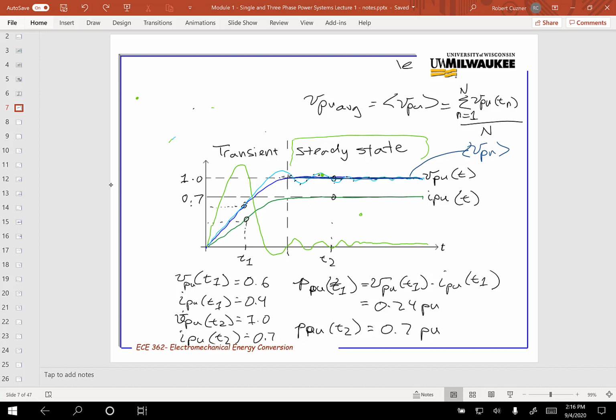So when we're making measurements on signals, or if we're making measurements in the lab, like you'll see in our power lab, we're using instruments. Instruments do some processing, some filtering, some averaging on the signals that are being measured, and this is what you're looking at typically. So there's a difference between a scalar value and what you're going to measure with a typical voltmeter, because the voltmeter is going to either average that, or it could do a root mean squared, an RMS, right?